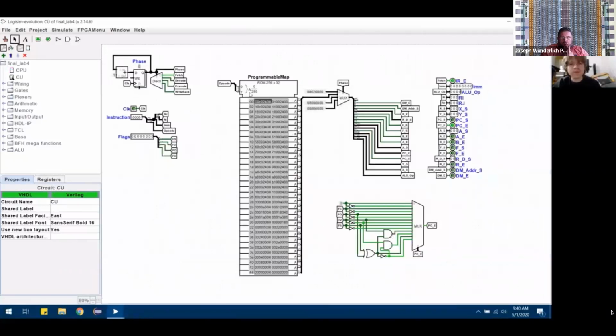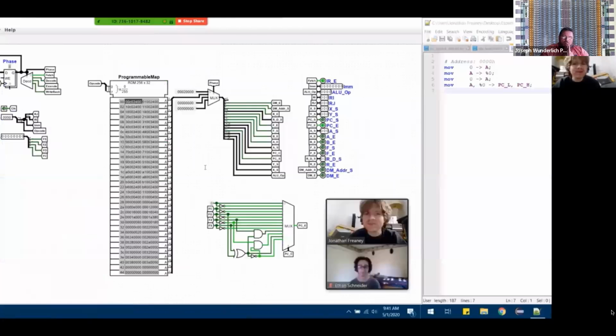Within here, again, we cheated our way out of this. This programmable map stores 32-bit words. There's 256 of them, 1 for each possible opcode. We've only utilized like 60-something of the actual opcodes you could have out of 256. That was kind of efficient, but also we still have a lot left to use. So the way this works is we were really lazy.